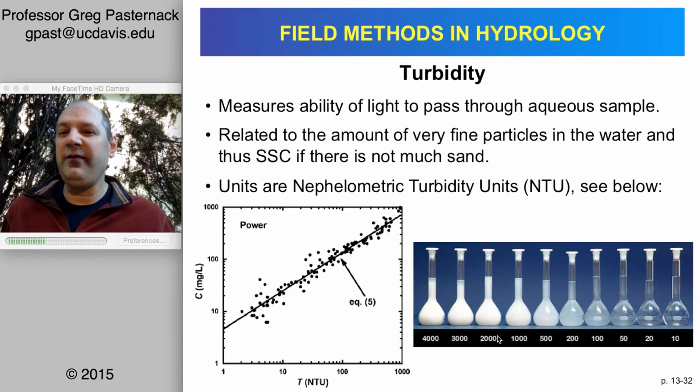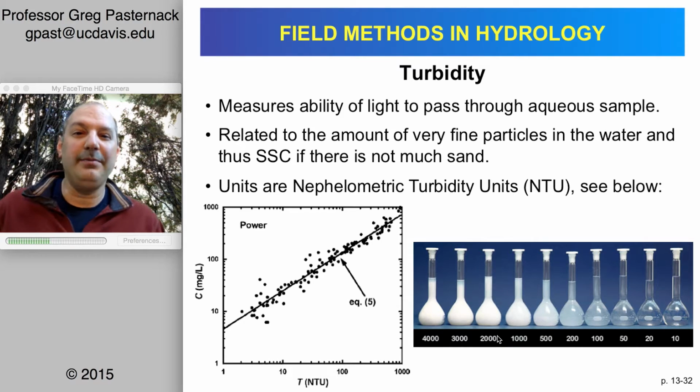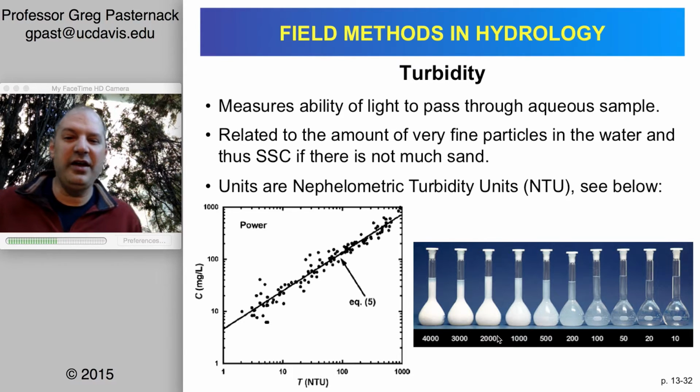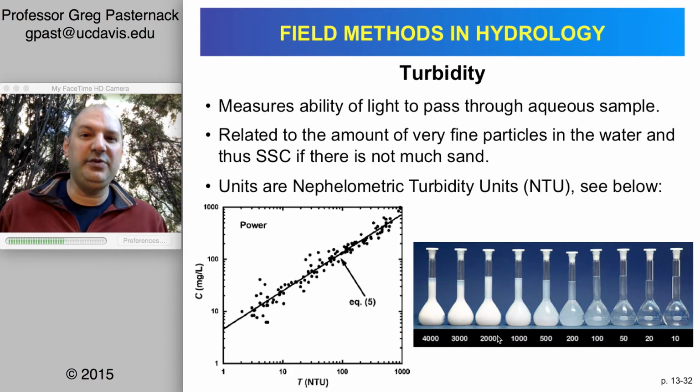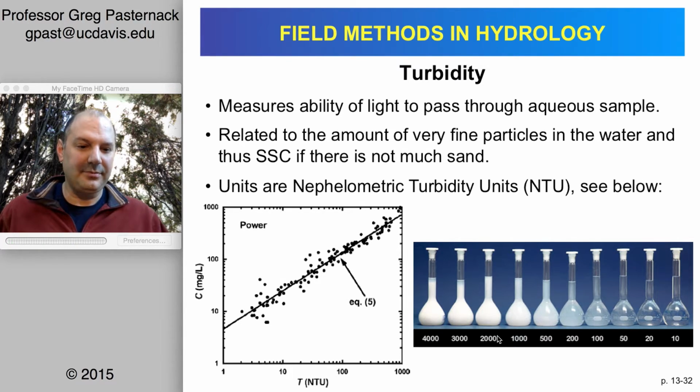For example, the very first slide, if you go back to the very first page of the video podcast, that lake with that bright blue color, coloration of water itself may not involve particles, but it could be dissolved constituents, and that can affect turbidity. Especially as we commonly see like a tea color if there's a lot of dissolved organic compounds. But predominantly the cause of turbidity, especially as a result of a storm or something like that, is going to be suspended particles.